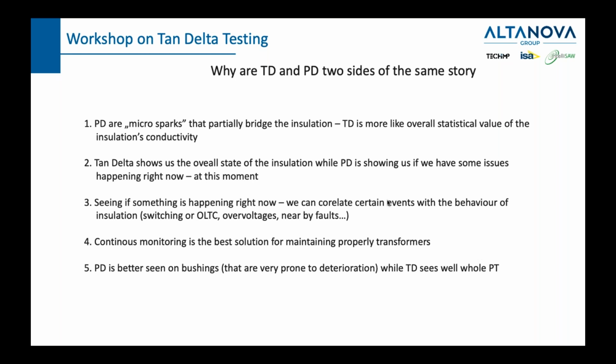Also, the best solution for properly maintaining not just the transformers, but all assets, is continuous monitoring. We had a lot of webinars on the topic of continuous monitoring. We will have them again. And we are now also implementing the continuous monitoring. We already did that on medium voltage cubicles, because on a medium voltage cubicle, you can monitor not tan delta, but for example, temperature and partial discharge. So soon we will have some webinars on that topic.